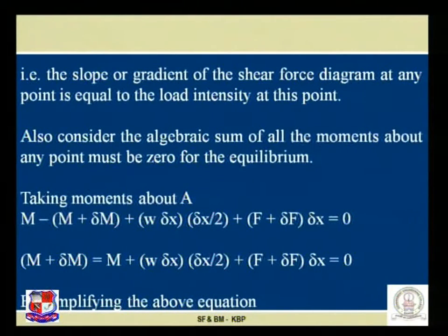The slope of the shear force diagram at any point is equal to the load intensity at that particular point. Now, after this derivation, let us consider that the algebraic sum of all the moments about any point must be 0 for equilibrium.